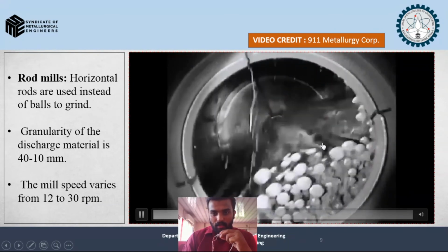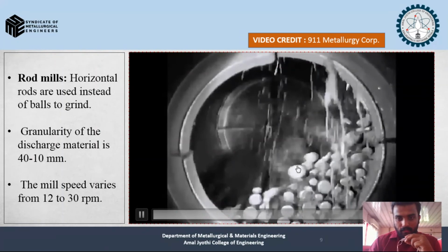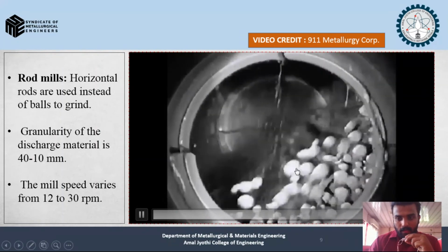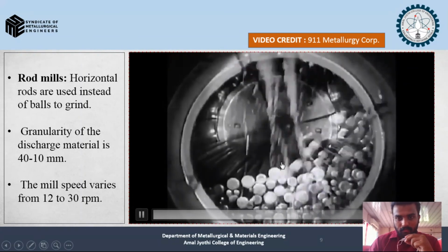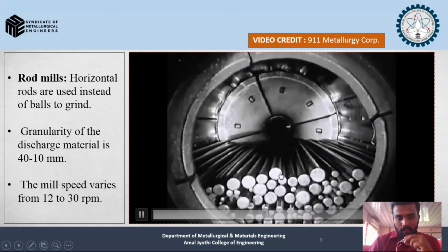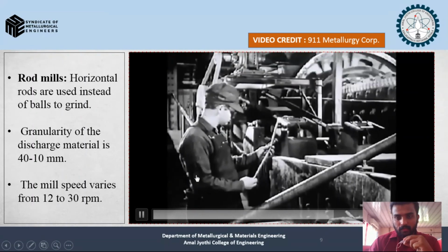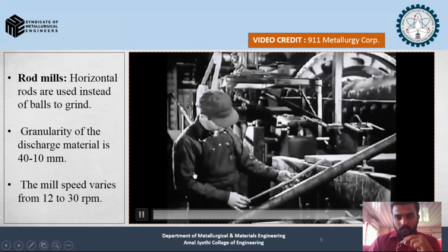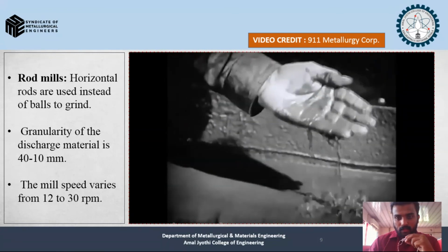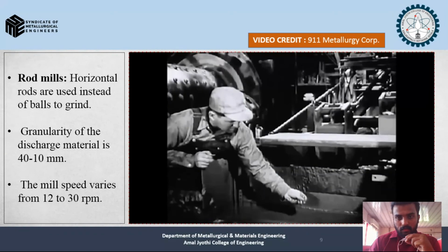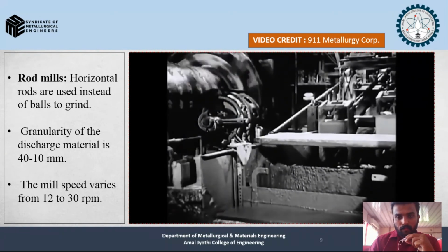Here's what's going on inside. 35,000 pounds of steel rods hammering against 28,000 pounds of rotating manganese steel plates, whirling around 17 times a minute. Tough going for the ore and for the steel rods too. This is what a 10-foot rod looks like after going through the mill. In the rod mill, much of the ore is ground fine enough and requires no further grinding. And this machine, called a classifier, floats the fine ore out and sends it on its way.